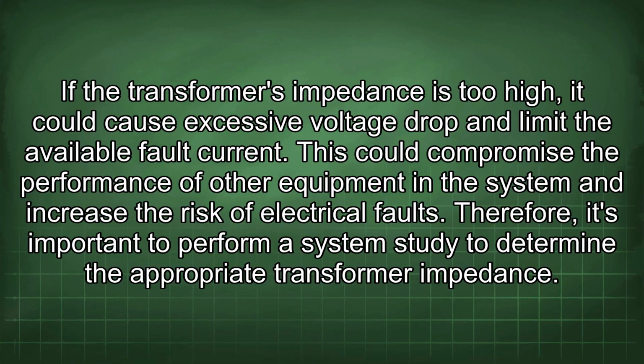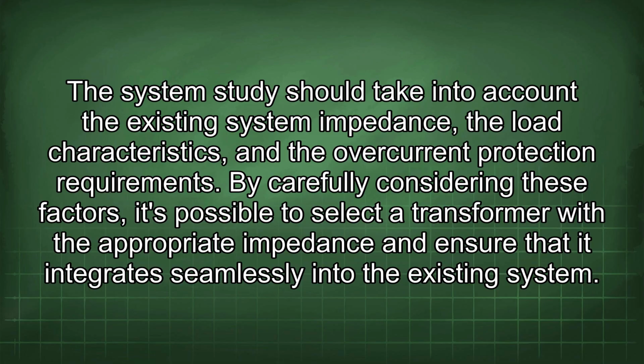Therefore, it's important to perform a system study to determine the appropriate transformer impedance. The system study should take into account the existing system impedance, the load characteristics, and the overcurrent protection requirements. By carefully considering these factors, it's possible to select a transformer with the appropriate impedance and ensure that it integrates seamlessly into the existing system.